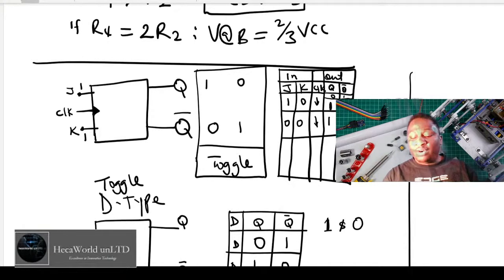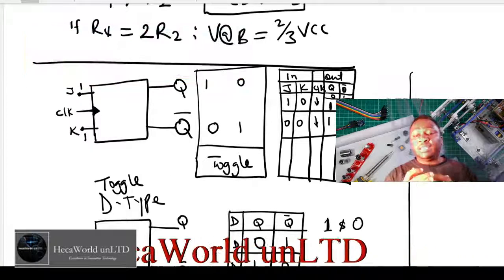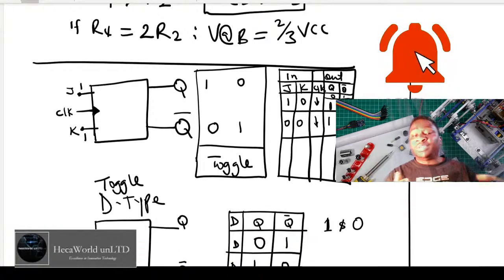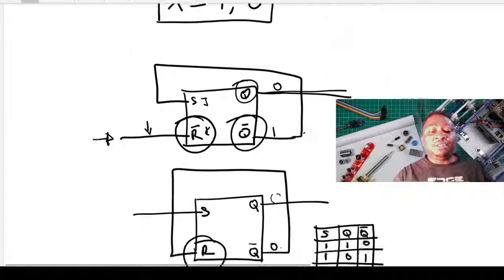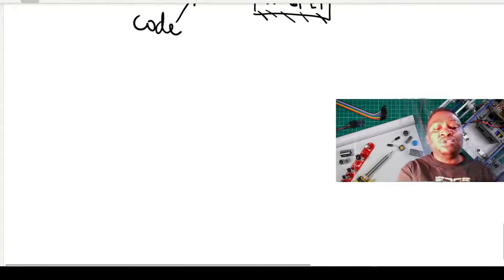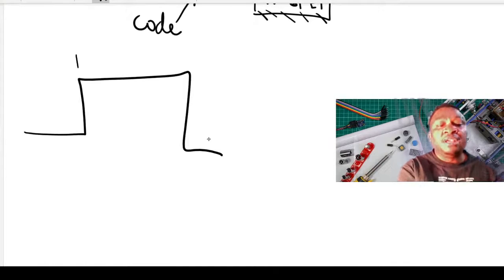When you get it wrong for so long, you enable a 555 timer, which will block you from doing anything else. The 555 timer simply comes on and gives a logic state, and that logic state is used through transistors to reset all your flip-flops and keep them reset until the time runs out. So we use the monostable interval. This period here is your monostable interval.